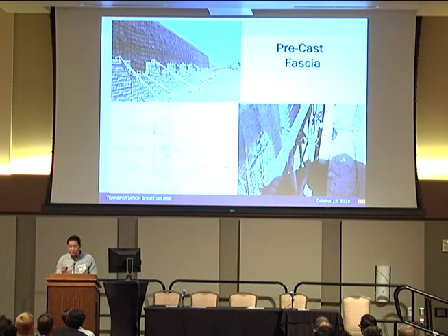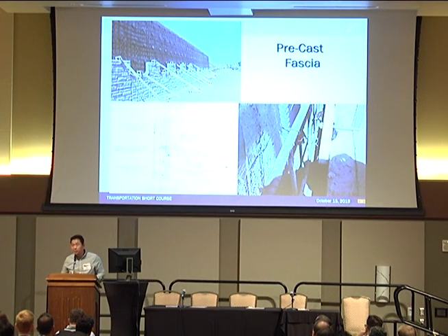Basically, you apply 4 to 6 inches of the first-phase shotcrete, then shoot another layer, and you can make a smooth face, or you can sculpt the shotcrete to obtain whatever aesthetic detail is required.